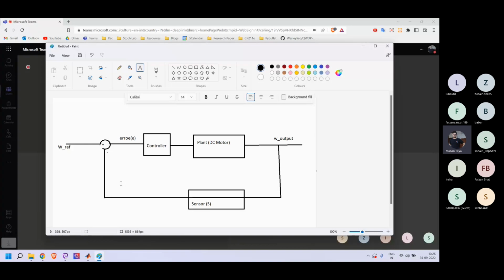It might measure 0.9 radians per second, but currently when we start building the controller, we start very simple and then we start modifying different elements of the sensor, different elements of the environment actually. So there might be some noises in the plant model or in the sensor model, right? So we try to later on add these things to the model, and then we modify the controller accordingly.